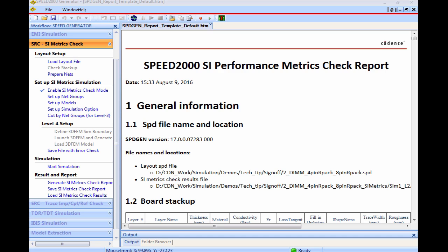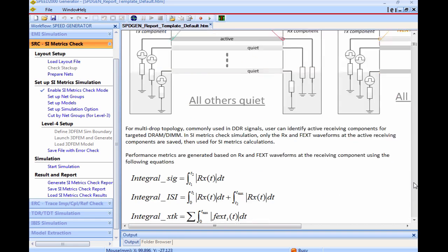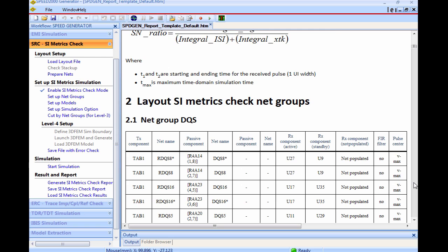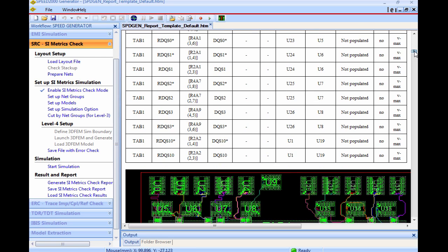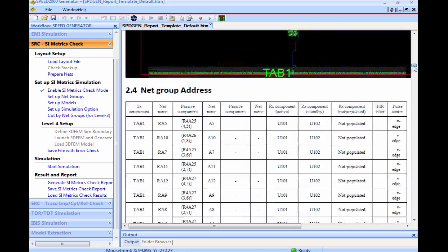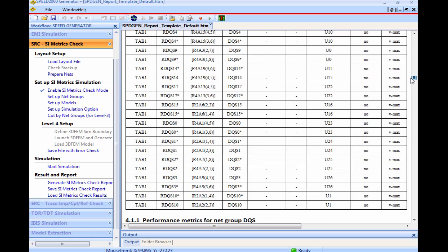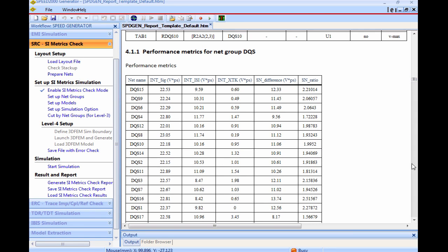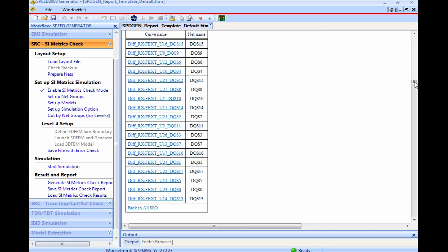The signal noise ratio and other parameters are all calculated with either ideal PDN or non-ideal PDN with the hybrid solver, or even the 3D solver as we selected before simulation. You can see designers can judge the overall signal quality based on the report and select some of the signals with high signal noise ratio to run more detailed analysis.